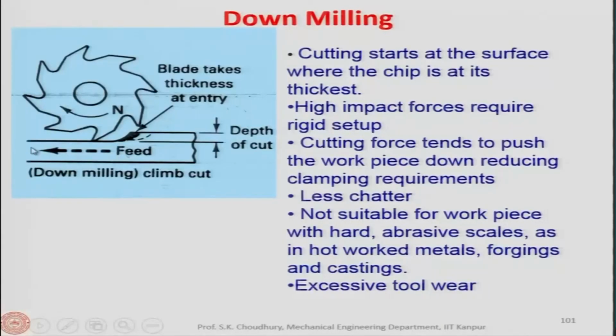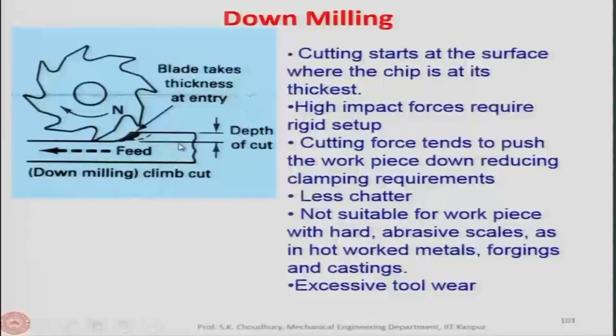There is a tendency for this workpiece to go towards the place where the operator is standing. So, one has to be very careful that if the clamping is not proper, in that case the tool may actually throw this workpiece towards the operator where the operator is standing. Now, chatter will be less, because here the chip thickness starts from the maximum, that is one point.